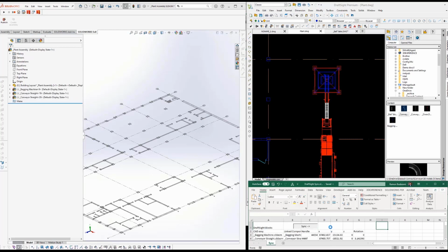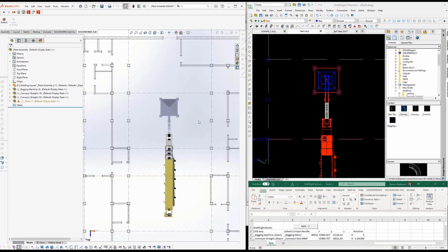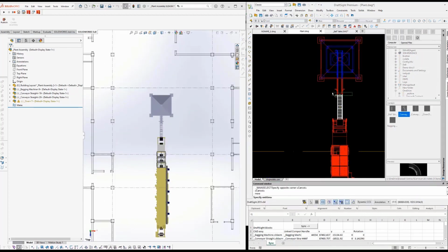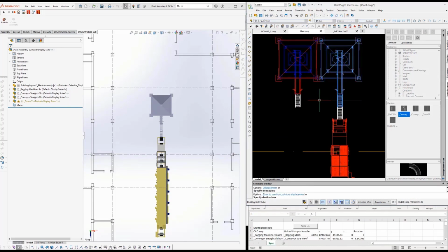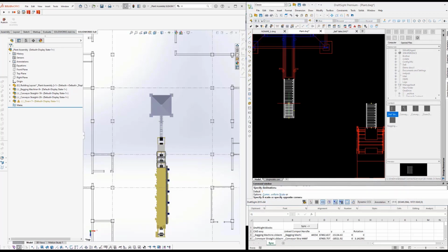It's going to create and insert those subassemblies inside SOLIDWORKS, so you can see where they're located. They're located in the middle of that column set, exactly how we have it shown in DraftSight. So no problem there. Now, let's go ahead and make some changes. The first thing is we want to move everything over and slide it closer to that column line. The next thing is let's add a T-junction in here. We're going to throw in another straight piece off of it and rotate that around so we can actually have a T.